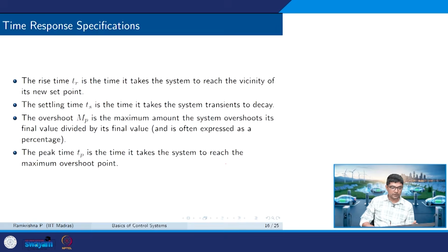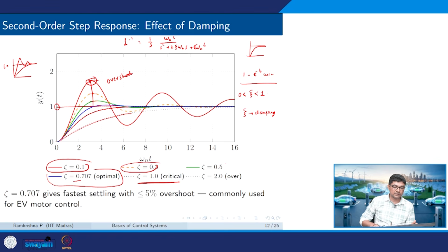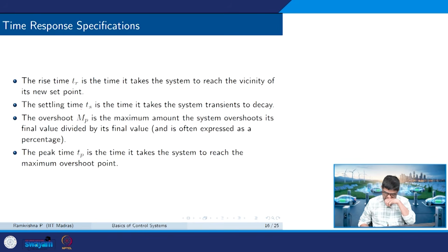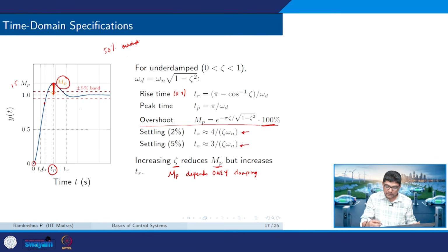But it may increase the rise time. What is the rise time? You see that the response becomes a little slower. It takes some time to reach the 90%. It takes a little more time, and so on. But that's okay. That's the kind of trade-off that you are looking for. And increasing the zeta, if the denominator increases, the numerator also does. So, it also has a good effect on the settling time.